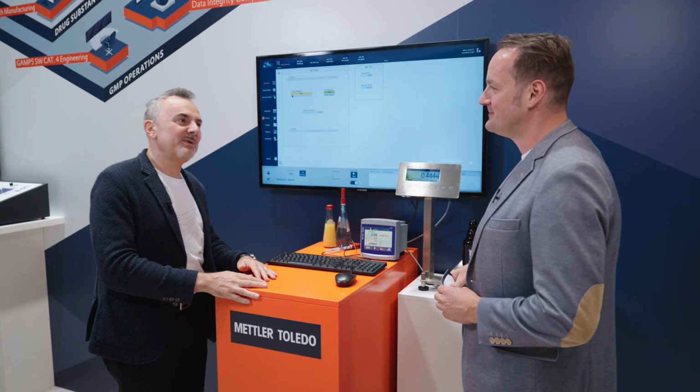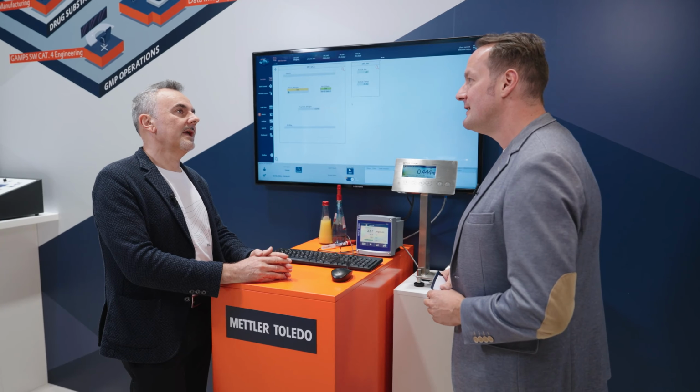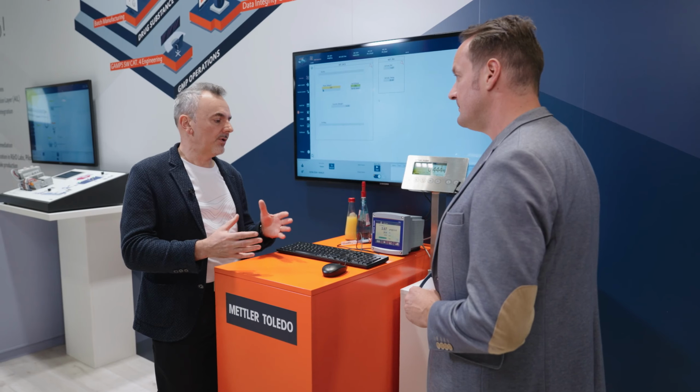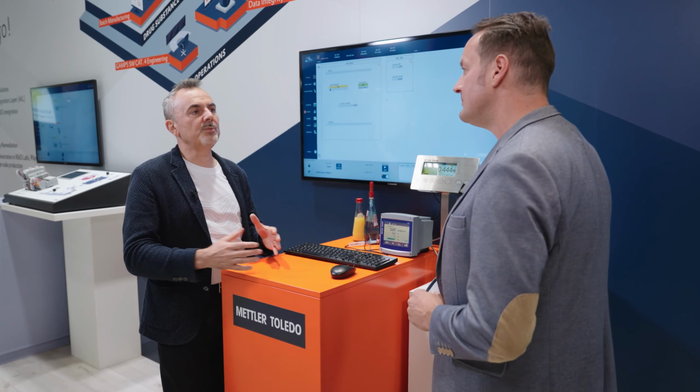My name is Giuseppe, and I'm Director of Life Sciences and Process Automation at COPA-DATA headquarters in Salzburg. So MTP, what does it mean and what does it stand for? MTP stands for Module Type Package, and essentially it is a vendor-independent description of a process module. And I would say it is exactly the basis for implementing a plug-and-produce approach for modular process automation.